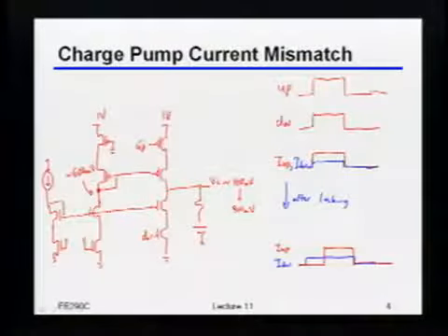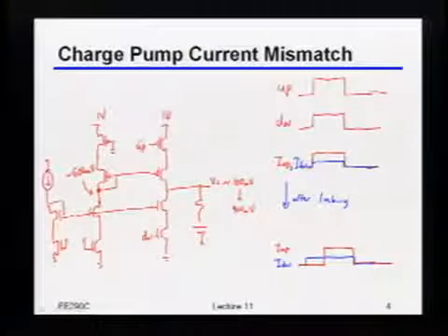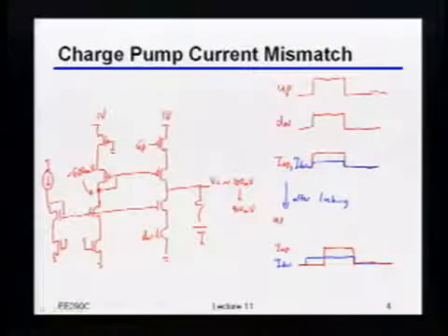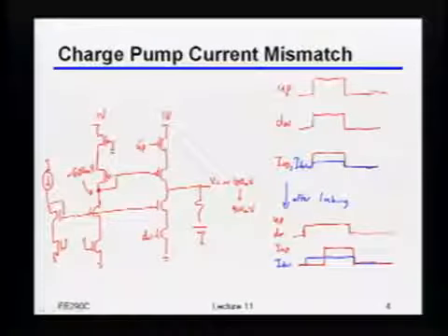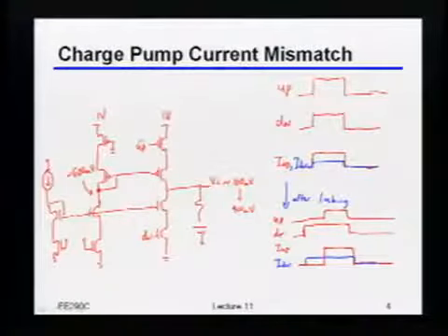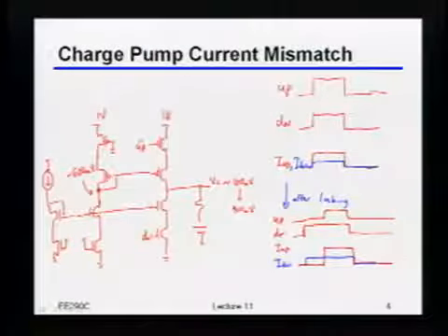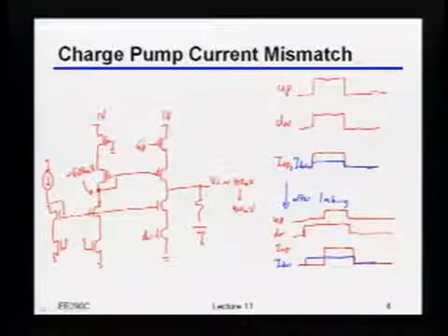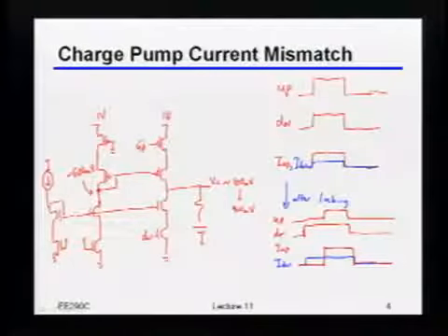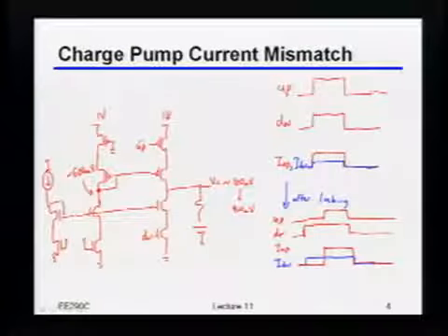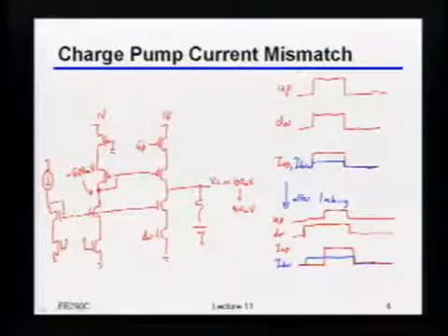Down always has to arrive first, right? Because if it doesn't arrive first, there's no way for you to get this waveform. So again, we can draw the up and the down here. Down shows up like this, and up shows up like that. In other words, this charge pump current offset is actually translating into static phase offset at the output of the PLL, because there's no other way for the PLL to lock or get those charges to be balanced except to skew those pulses against each other.